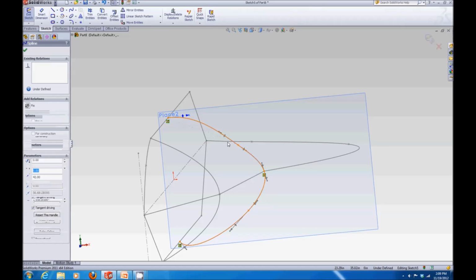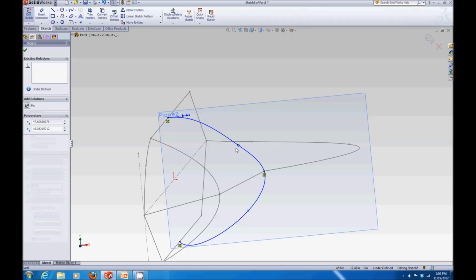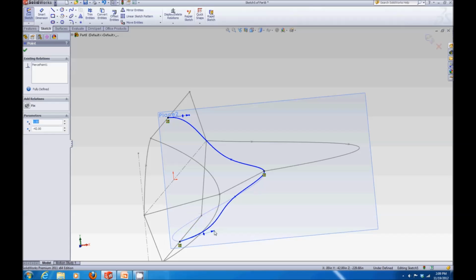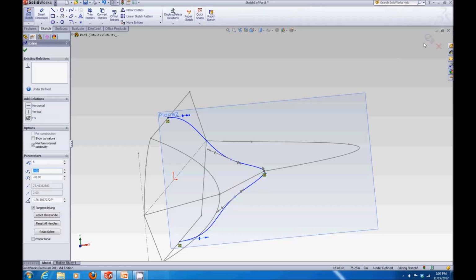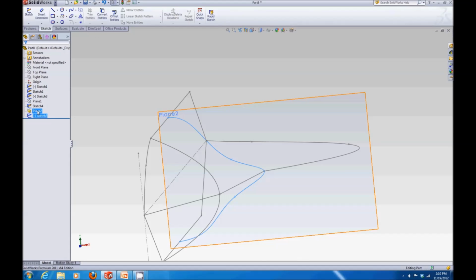This could be our cockpit section, and our cockpit ends right there, and we want to blend it with our wing, so we could add some blend here. The bottom one we can adjust for the cockpit again. So this would add a slight blend for the wing. And then again, we can hide that.